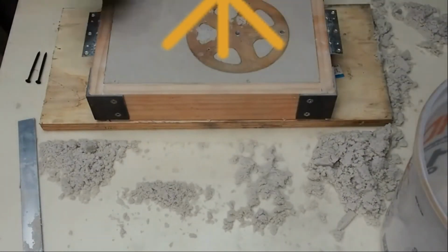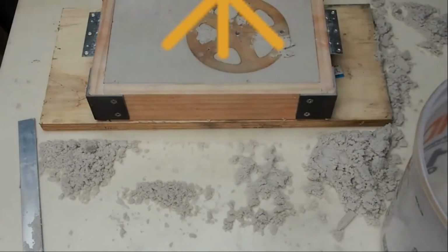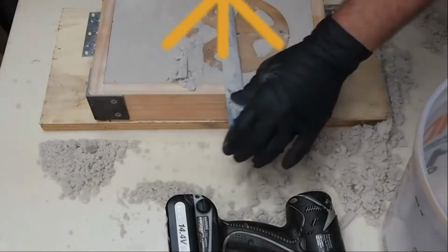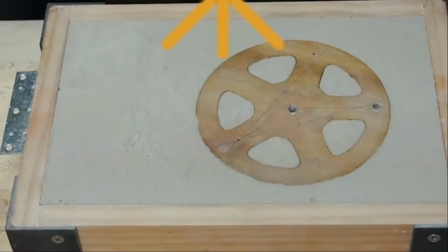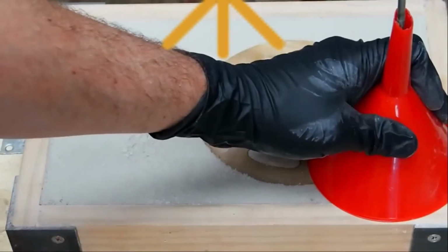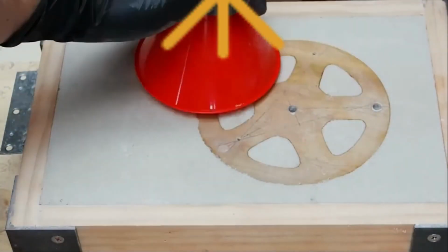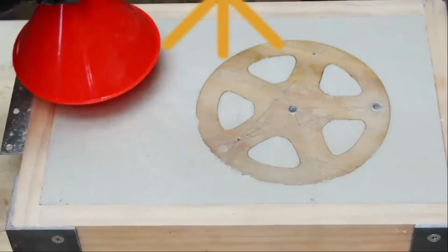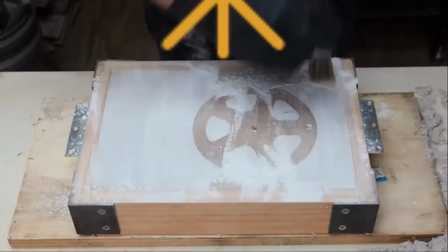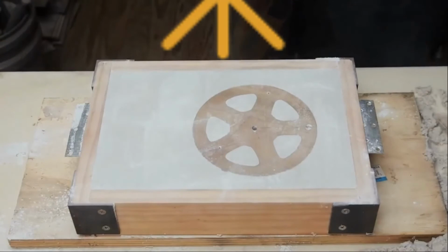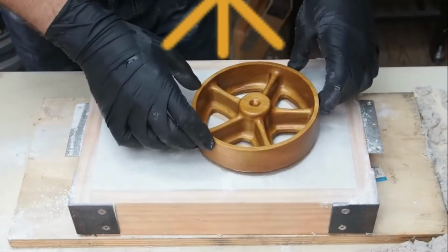I am adding screws here to help support the deep mold cavities. Here I am flash curing the mold with some CO2. This penetrates about an inch and gives at least a little bit of strength to the mold. Here I'll be using talc on the parting line, and I probably should have left a little bit more as it ended up sticking a bit.